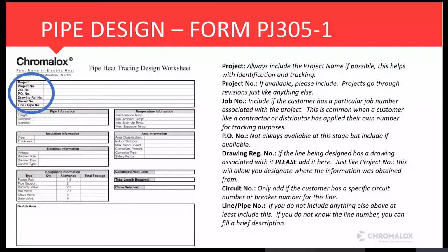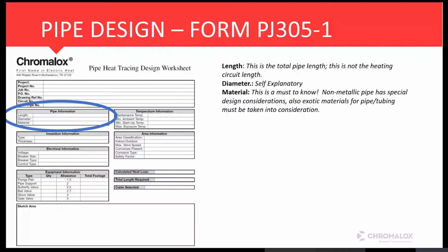Moving down on pipe information, these three are obviously a must. Your length. Keep in mind the length is your total pipe length. This is not your heating circuit length. This is the length of the pipe. So always remember that. And I'll get a little bit more on that here in a second, but remember your length is your pipe length.